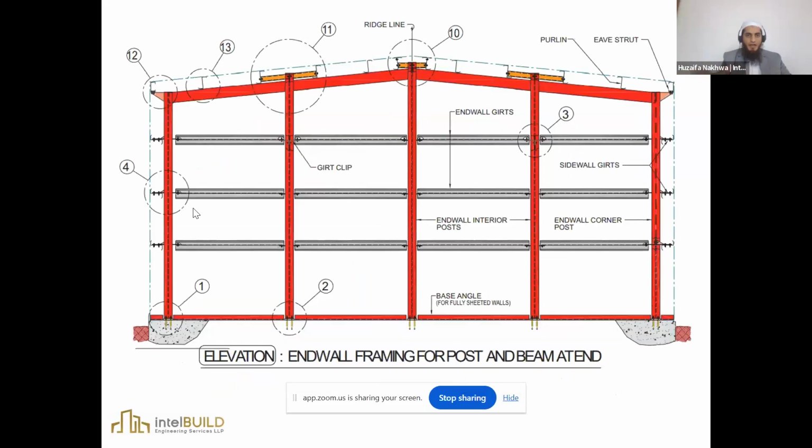So this is the end wall arrangement. In the end wall frame, you have to provide the columns at certain intervals, because there will be sheeting on the end wall.